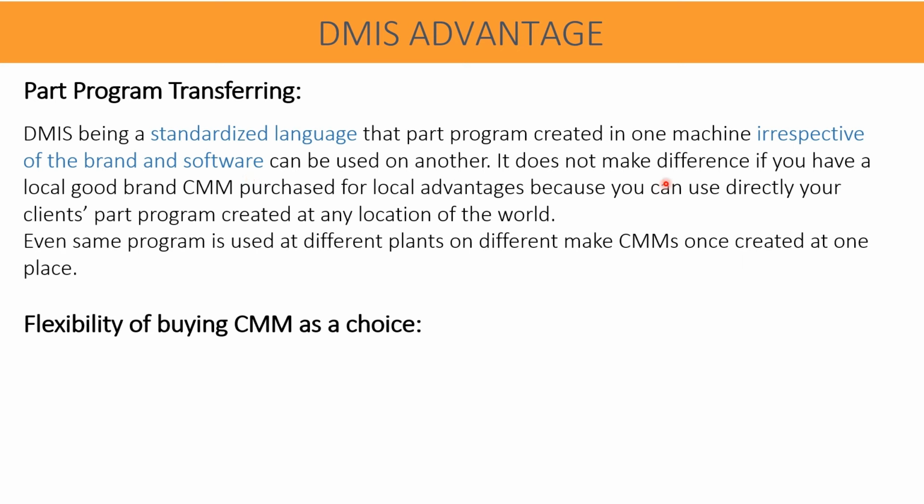It doesn't make any difference if you have a local good brand CMM purchased for local advantages, because you can directly use your client's part program created at any location in the world. Even the same program can be used at different plants on different make CMMs once created at one place.